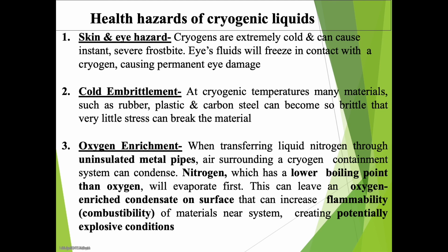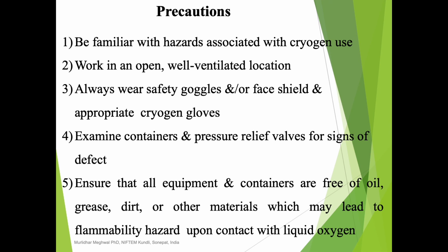There can be cold embrittlement. Materials like rubber, plastic, or carbon may become very brittle at reduced temperature, and these materials may create some problems. So one should be careful while handling. And there may be oxygen enrichment, which may lead to flammability or fire hazard. That should be avoided, and precautions should be taken.